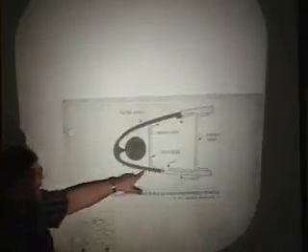The downside is that this leading edge of the wing here is made out of aluminum. Aluminum melts, I mean liquid, at 1100 degrees Fahrenheit. If you heat it up more than about halfway up there, 600 or 700 degrees Fahrenheit, you're going to start destroying the strength of the aluminum. It won't melt at 700 degrees Fahrenheit, but its strength will be dramatically reduced.